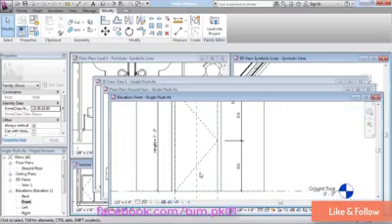So what I want to do is, for the two bathrooms that we have back in our project, show that there's a louver down at the bottom of the door. Now, there's a few ways we could approach that. We could actually model the louver three-dimensionally as a full-blown 3D model. That might be a little bit overkill. It would be heavier, it would increase the file size, and it might show too much line work, and it wouldn't look so good when we print it or when we display it at smaller scales.